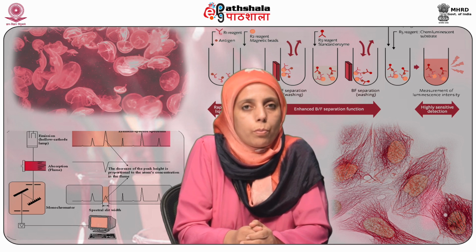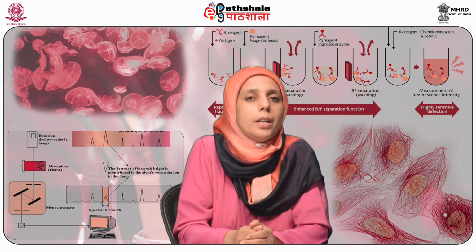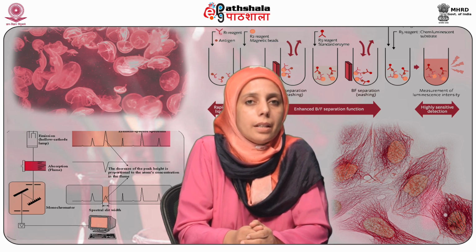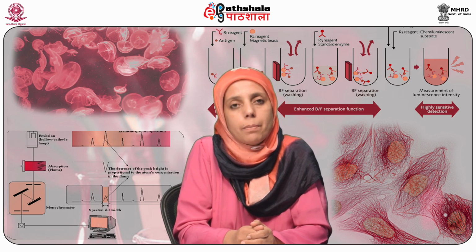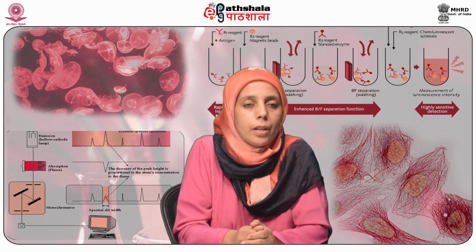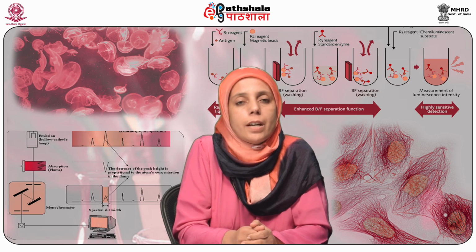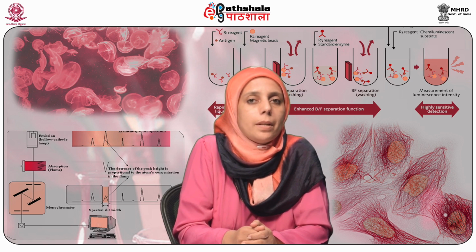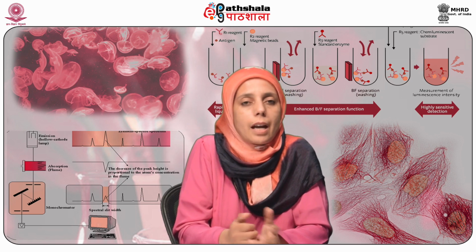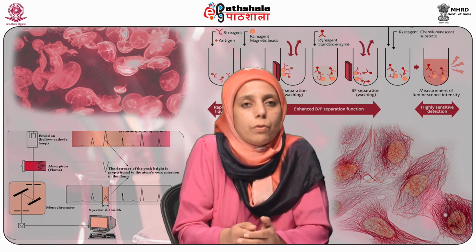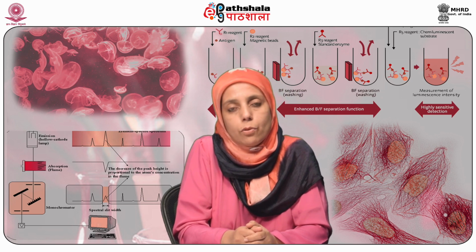Atomic absorption spectroscopy is not generally preferred for arsenic detection due to poor detection limits, that is, less than 1 milligram per liter, because the limit of arsenic in any sample is very low, in parts per million. So therefore atomic absorption spectroscopy is generally not preferred. Once the decision is made, the sample is analyzed by the instrument as per the instructions of the manufacturer. The standard protocol has to be followed as per the manufacturer, and it is given in Table 4.